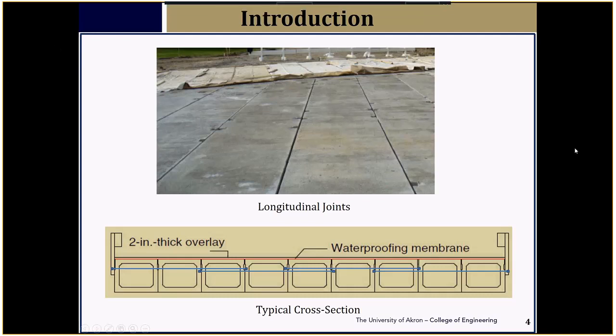A typical box beam bridge will have a series of boxes. In ODOT standards, we tie three boxes together, and then there is an overlap of ties. The goal is to ensure that all the box beams work together as a single unit. The tie rods are 1-inch tie rods. They're not really post-tensioned, but just snug tight.